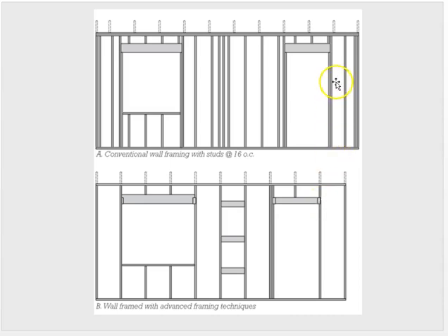So up here, where we first put in our doors and our windows, and then we had to come back and count every 16 inches to put the remainder in, it was clear that the doors and the windows were not laid out on that increment. Here, however, we have a 16-inch bay, I would call that, and then we found a 32-inch door and we put it right on that increment. And then again 16, 32, 48, and then we started our window, which again is 48 as well. So that I definitely appreciate, and if I were designing a house for myself, I would do that. I would not remove the double studs though.